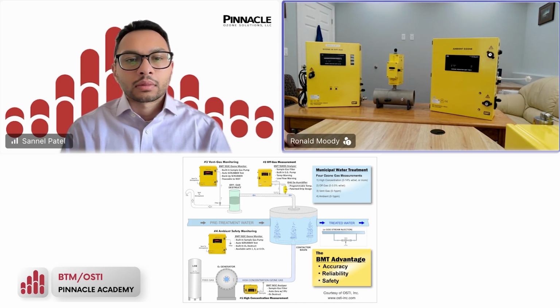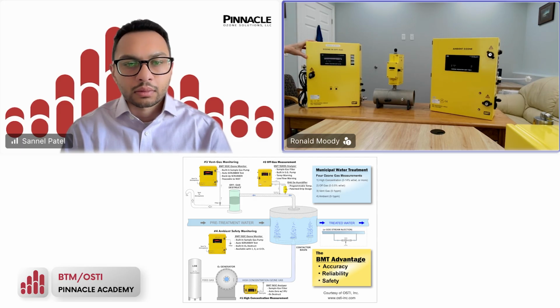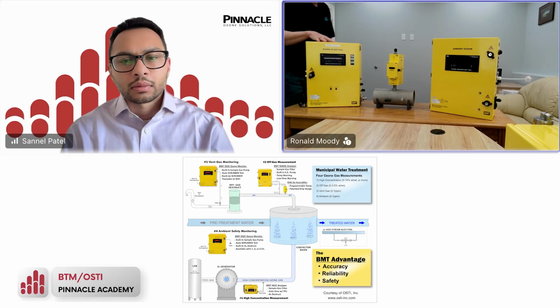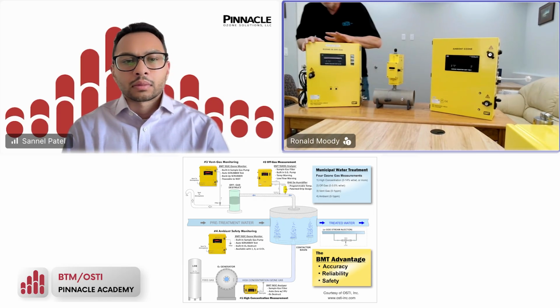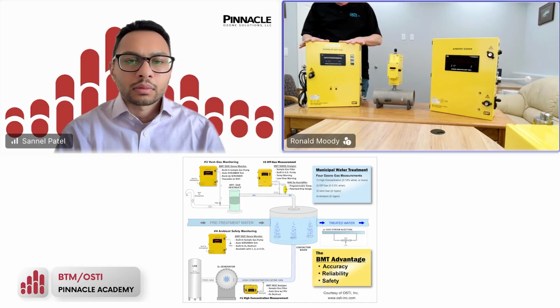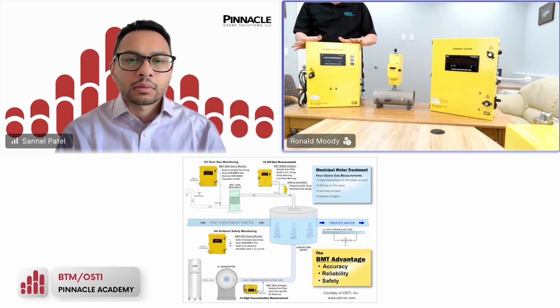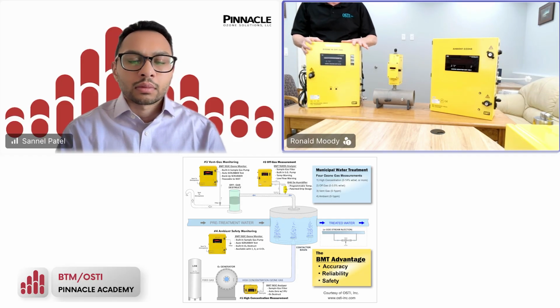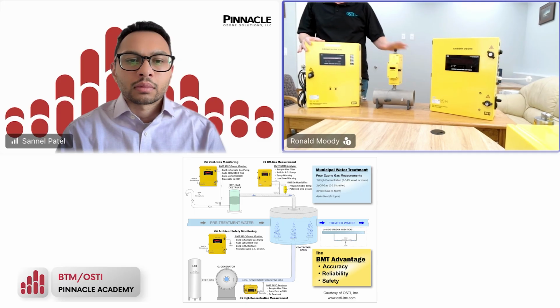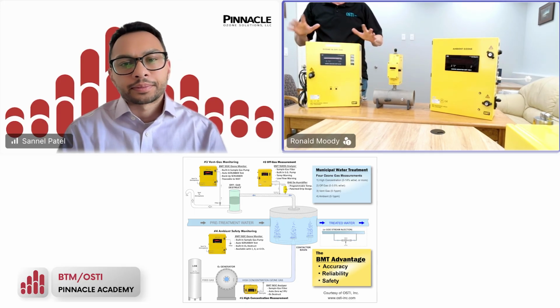So after the high concentration measurement, the second measurement point for us is the residual off-gas. This is an example of an off-gas analyzer, and I'll walk around here to kind of illustrate a couple things. Before I demonstrate that, I will say, though, that the second sampling point in a typical water treatment plant might actually be dissolved ozone along the path where it's being exposed to ozone. This actually isn't a good use for ozone photometry, primarily because there's quite a bit of microbial and particulate matter still in the sample stream.